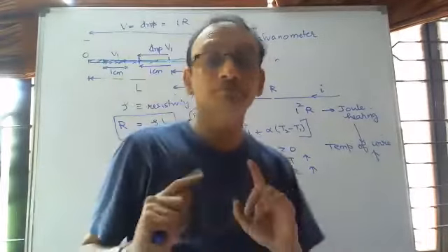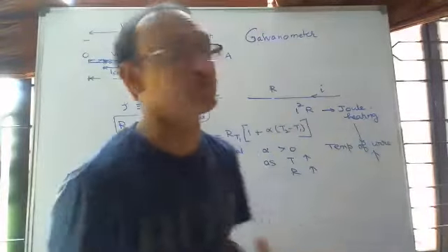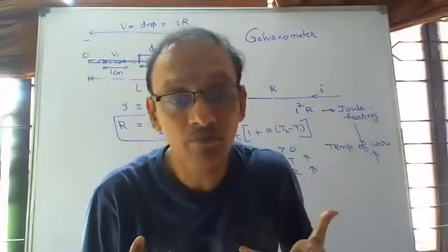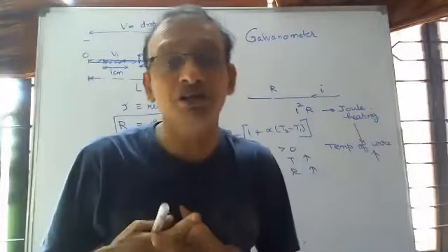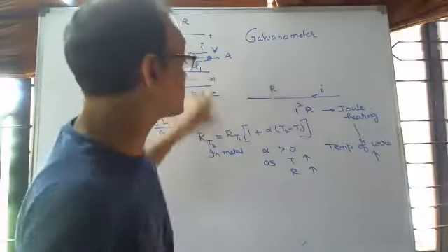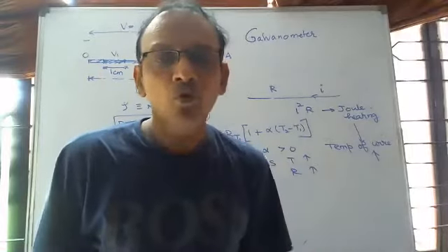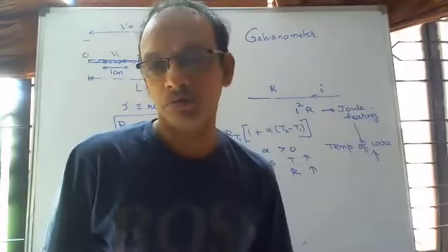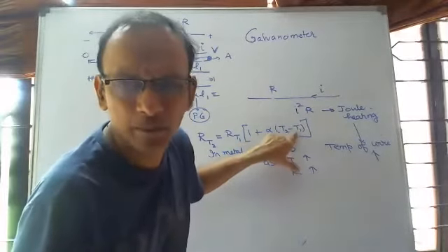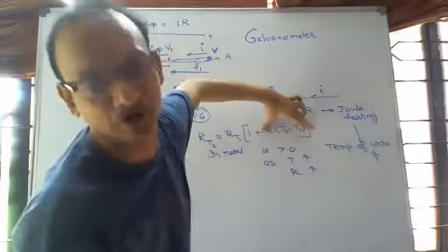Problem will be if I'm dealing with a wire and I'm using some standardization around that wire. इसका अगर resistance ही बढ़ता जाएगा, तो I'm in trouble, right? That'll be difficult. So what I want is a material, and alpha depends on the material. I want a material whose alpha is really, really small. If alpha is really small, then alpha delta T would be negligible, 0 के बराबर होगा, so RT2 will be equal to RT1 approximately.